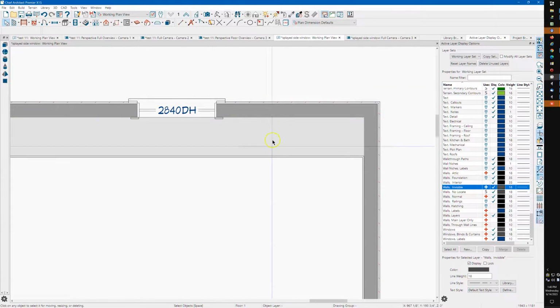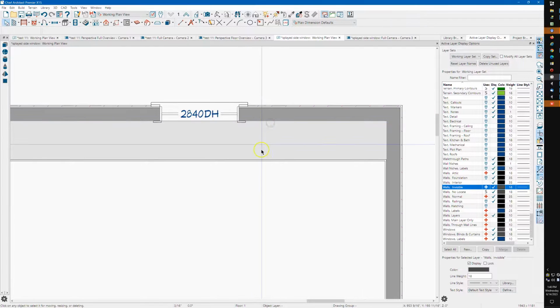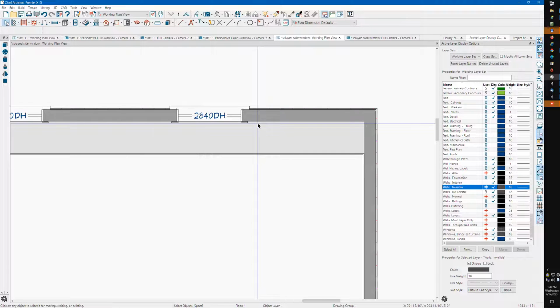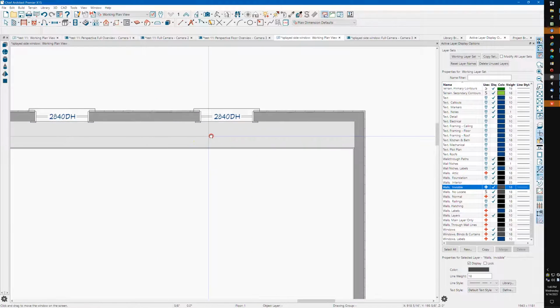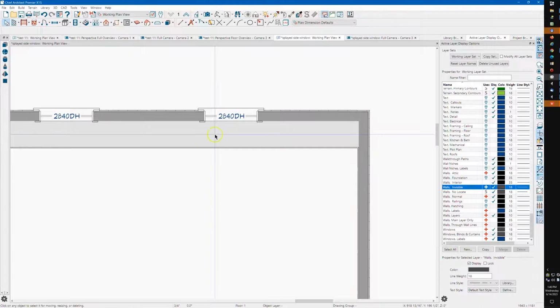You can actually do what I'm going to show using a single wall, but because of the way Chief windows work, you'll lose the casing on the inside, so you would have to draw in your casing manually. So that's an option. But I'm going to show how to build a symbol that you can use here.